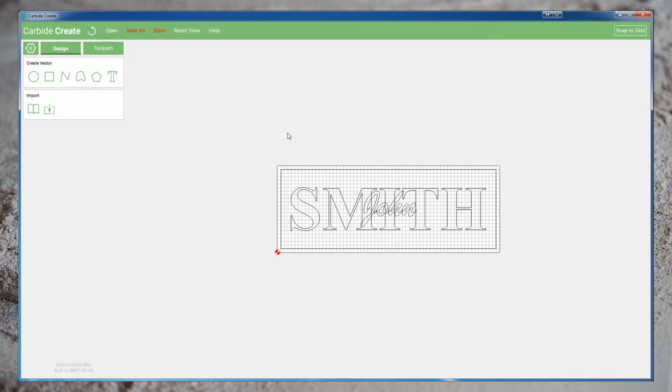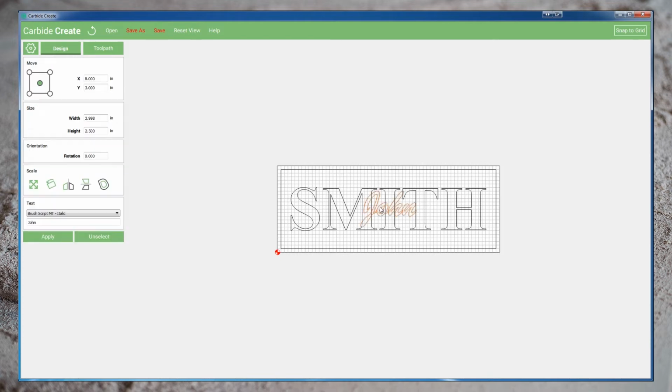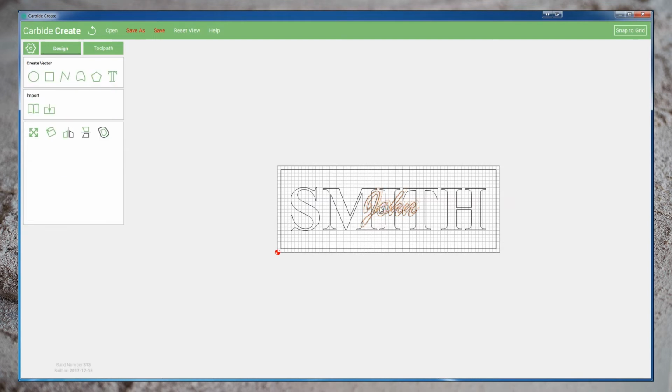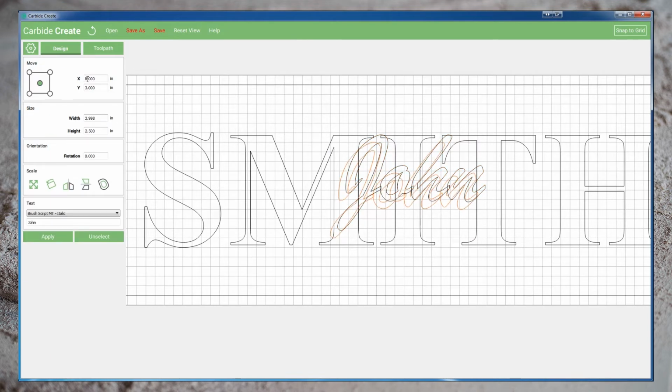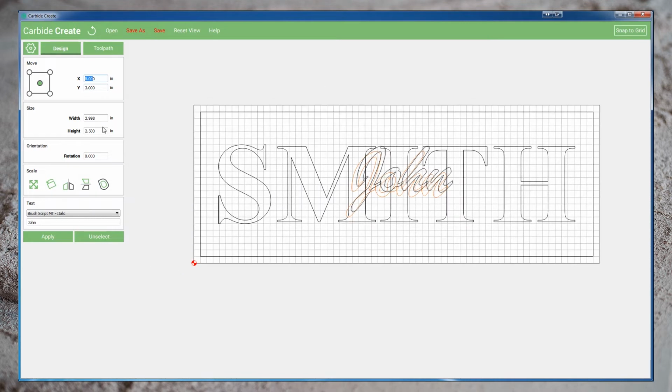Just as in my last video, we'll now use Boolean Operations to create and bind shapes that we can use to define our profile cuts. We'll start by clicking on the top layer, using the Ctrl-C shortcut to copy the element, and then we'll zoom in, click on the original element, note its location at 8 inches by 3 inches, select our new element, and reset its coordinates to that same 8 by 3. You can now see that the two duplicated text layers are overlapping each other perfectly.